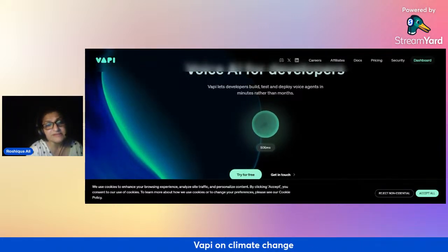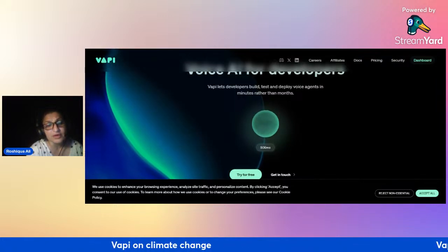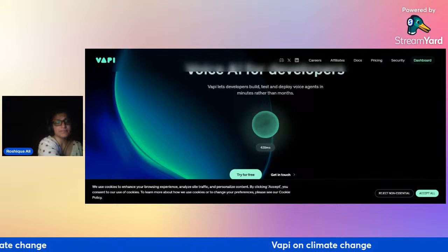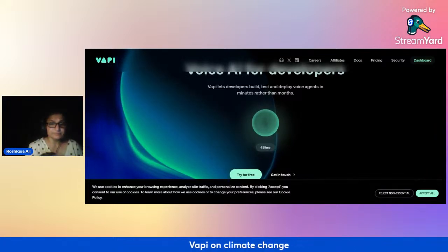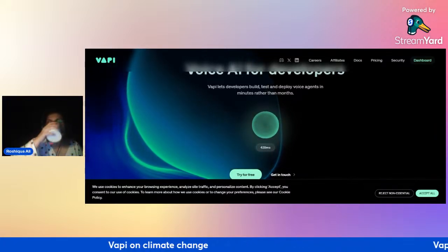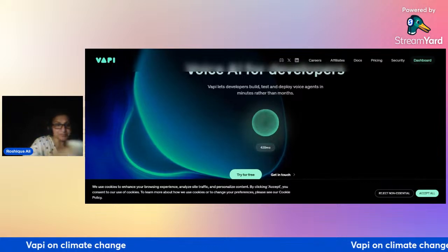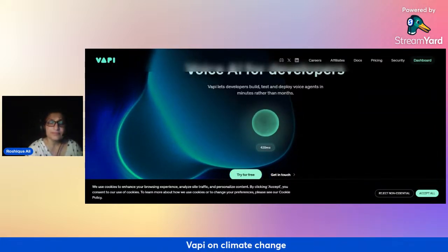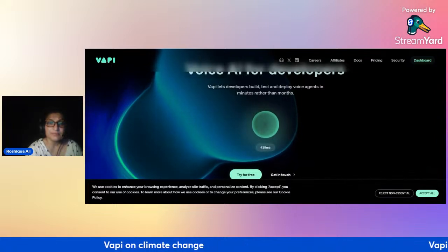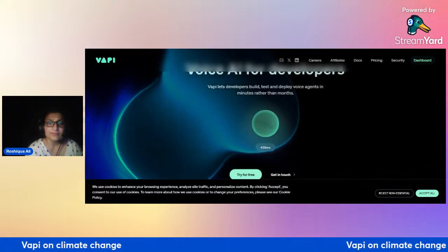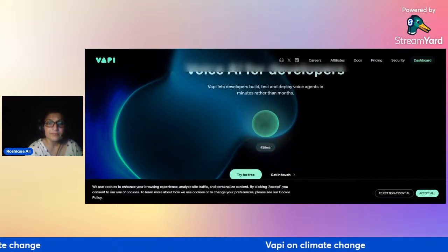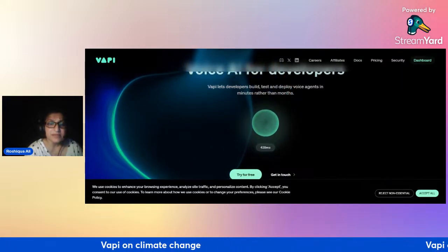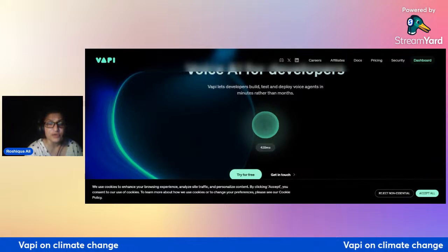So, thermal mass, what material would you recommend for a place like Pakistan? For a place like Pakistan, materials with high thermal mass like adobe, brick, or even concrete can be effective for maintaining a comfortable indoor temperature. These materials can absorb heat during the day and release it at night, helping to keep the interior cool. It's all about working with the natural climate to create a more comfortable living environment. But didn't you say that concrete is not good for the environment?